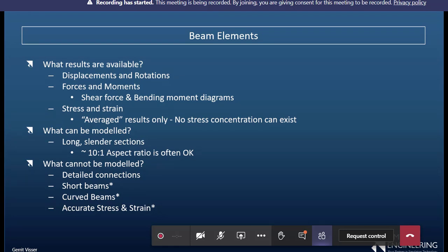So in other words, if I have some kind of a pipe with a radius going to another section, again, you cannot mesh that elbow section, the radius, using smaller beam segments and just apply straight properties to that, because you'll get the wrong answer. There are special beam element formulations that can do that correctly.